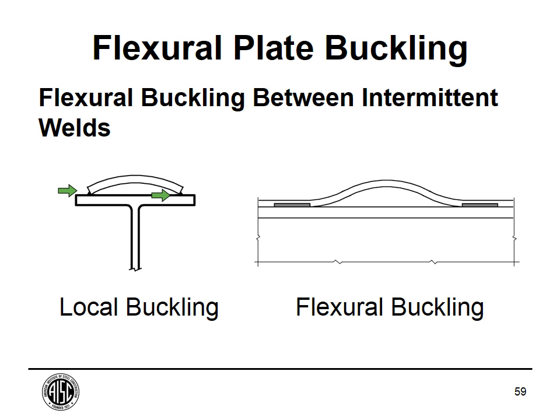So now let's talk about flexural buckling. Now this is on the length of the beam this time, looking at the web, or it could be a column turned sideways. This is the flange, and then you can see our plate buckles between the stitch welds that I've got shown here and here. So we need to prevent that. And everything I'm going to talk about is how to make sure that flexural buckling doesn't control the design over local buckling.